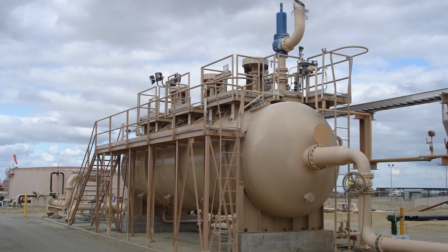If the nozzle has a piping connection like this, it will definitely have contraction and expansion due to temperature and pressure, especially temperature change. There is also flow coming from the piping line, like liquid flow or gas flow. Because of this kind of flow and vibration along the piping line, there will be loading. All this loading is distributed along the pipeline and finally impacts the nozzle face of the pressure vessel. Therefore, there will be nozzle load wherever outside piping is connected.